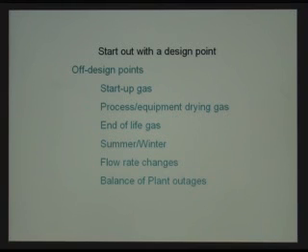Summer and winter considerations, especially if you have a gas turbine and especially if you have large ambient temperature swings, the horsepower that you have from summer to winter can be extremely different, and how you operate your machine and how you size your machine becomes very dependent on this horsepower swing, and we'll get into details on that a little later on. Flow rate changes: if you know that you're going to have large swings in flow rate, then to be able to stay on the operating map, we need to make the map as wide as possible, potentially sacrificing in some other areas.